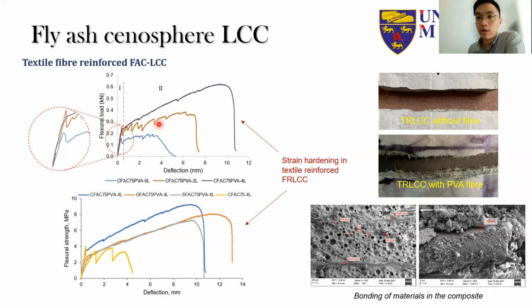So you might wonder why we do not just increase the amount of fibers instead. The reason we are not doing this is because it is usually much harder to incorporate high amounts of fibers, let's say 2% or 3%, and that might involve adjusting the mix, which might require much more binder content, and in turn this increases the density of your material.